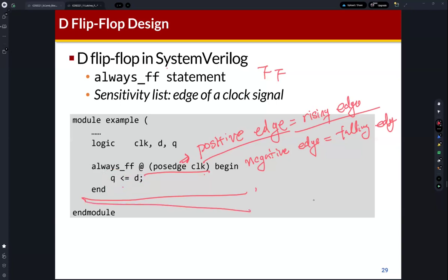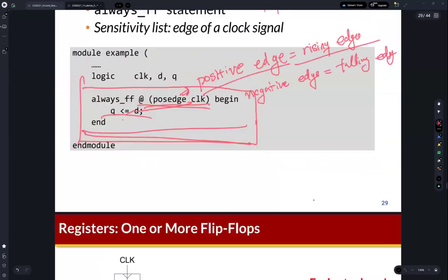Flip-flop implementation in SystemVerilog. So it's not a problem. As I mentioned, we frequently use flip-flops in this system. So inside of always_ff, we don't need to define the else state. In this example, I just define Q equals D, but it is executed on the rising edge of the clock. Okay, so transparent.